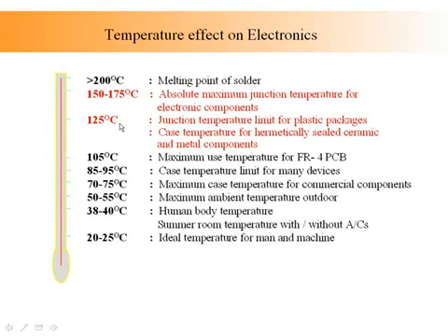Typically, 125 degrees C is a maximum that we will allow. So most of our designs, we will actually stay about 10 degrees cooler than that. So the limit is 125. Now when you go to microwave and wireless devices, gallium arsenide, this is silicon 125. Gallium arsenide, which is used in wireless applications, typically we will go in the range of 150 to 175, but we will definitely not exceed 175, and typically we will stay below 150.